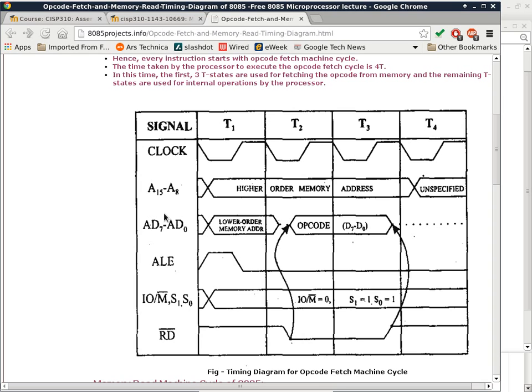Okay, and then on top of that, how do you get a signal, an electrical signal, from the top layer to one of these layers? Holes. They're called vias, V-I-A, vias. So a via is used, sometimes it can be plated, and with these boards, you can have vias that only go between certain layers, not all the way through, because you just want the signal to go from this layer to this layer here.